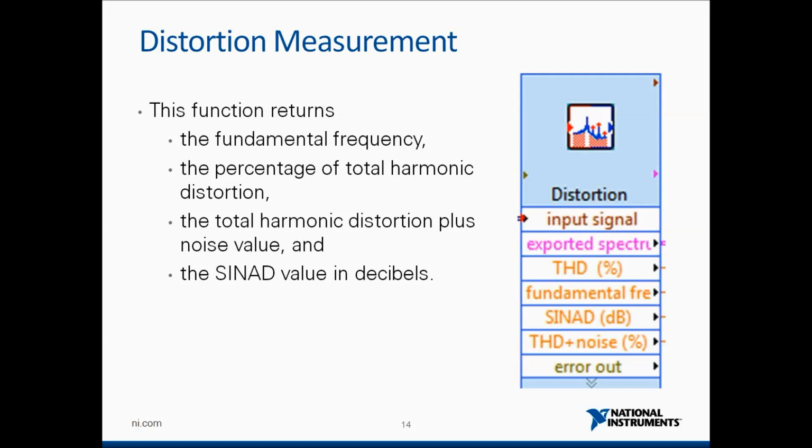The first one is tone measurement. What this tone extraction VI does is, if you give an input signal, it can detect the amplitude of the highest frequency and the phase also of that. So if I give a time domain signal, a sine wave of 100 Hertz, the output detected frequency would be 100 Hertz, and the amplitude would be the amplitude of the corresponding 100 Hertz frequency. Fine.